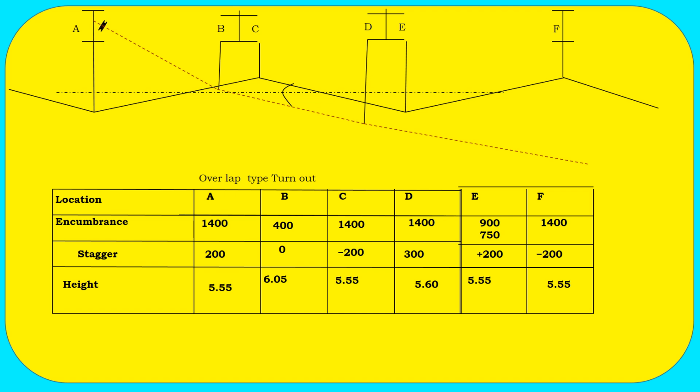This accurate adjustment is required here. One is leaving the mainline and catching the turnout OHE, that is 650 to 710 possibly, and another condition they have given is that within 10 meter from the center of that obligatory mast, the catching of the turnout and leaving of the mainline will happen.